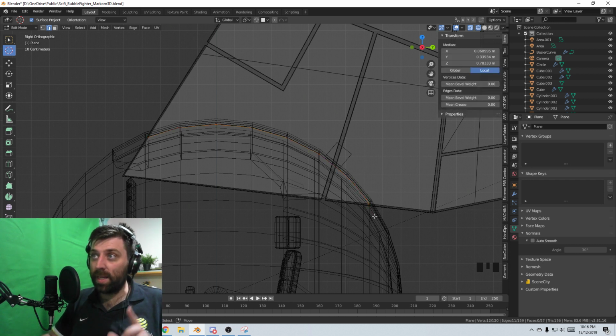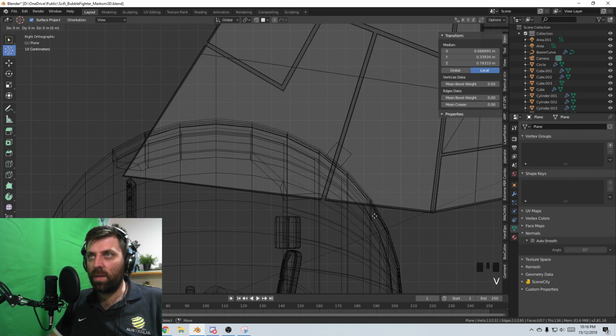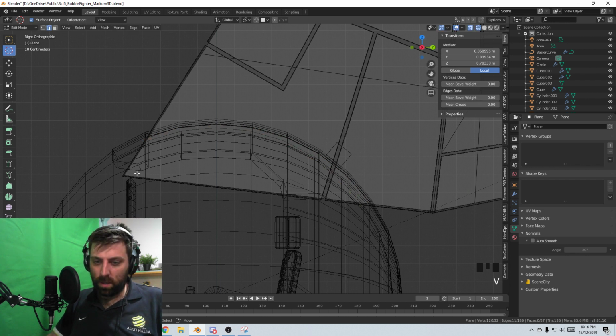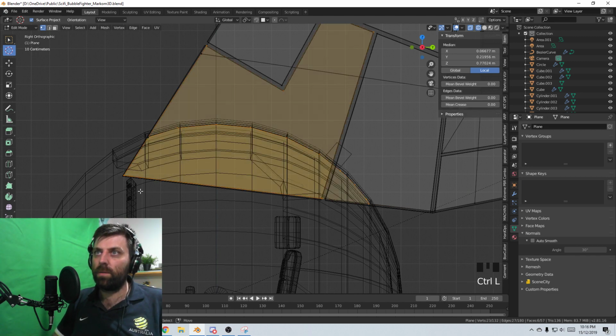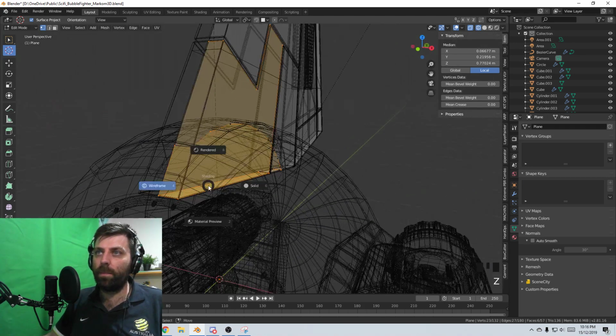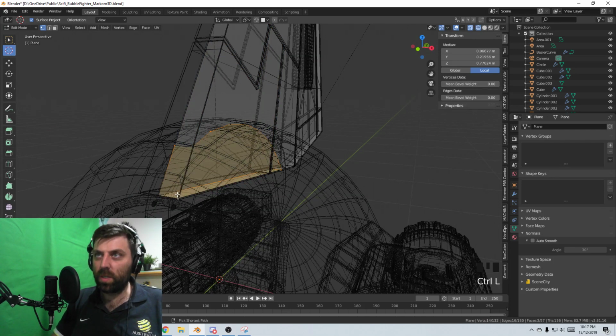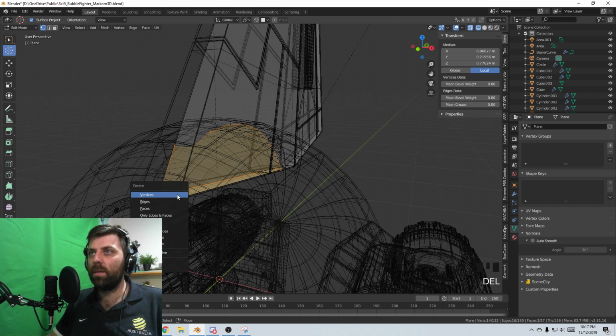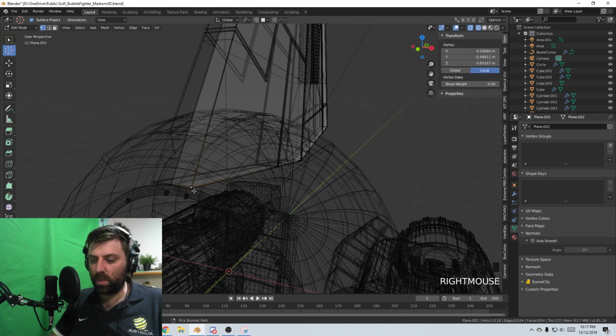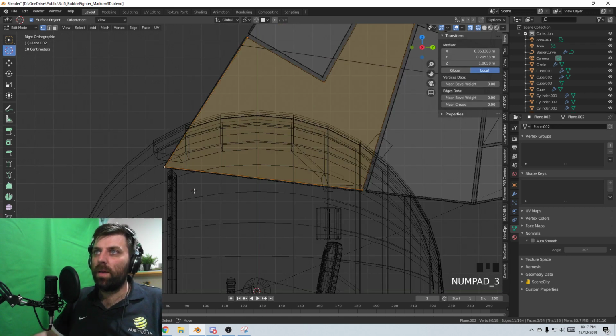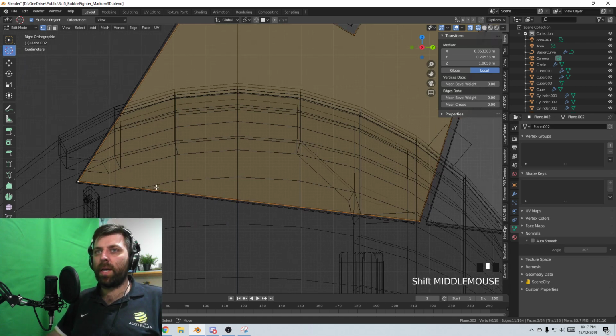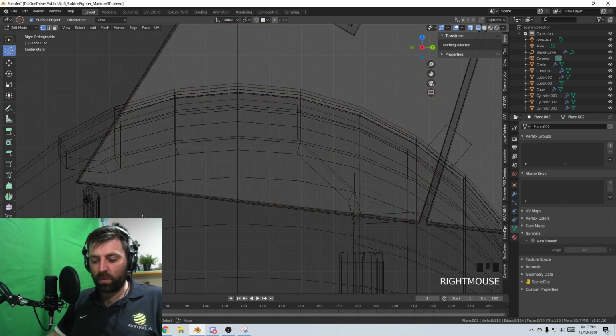I'm going to press enter, V to rip, and then I can come in and select all these vertices in here. Control L. I hate you. Why? Which one's the problem? Control L. Delete vertices. Probably because I can't do knife tool through two objects. So let's go back.